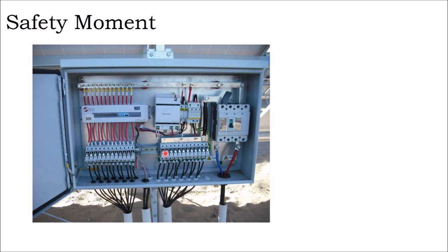Well, it can occur inside your combiner box. You could have a loose connection come out, and then you could have condensation coming up and creating a puddle inside your combiner box. If the water gets high enough, there you go. You don't even need to have a fault in your wiring if your combiner box fills up with water.